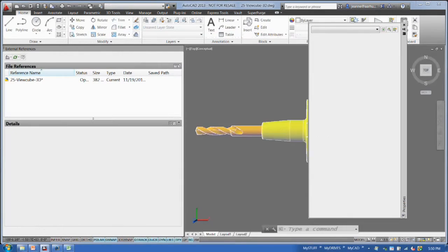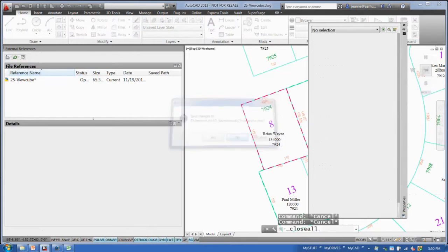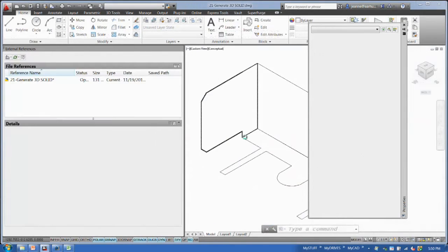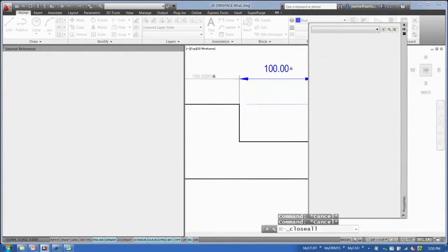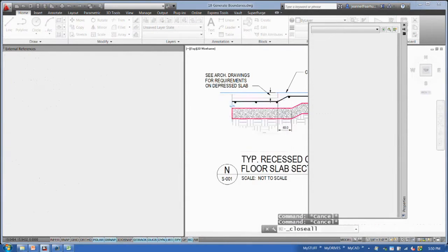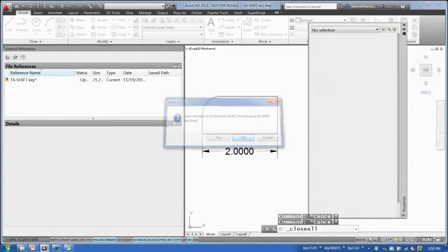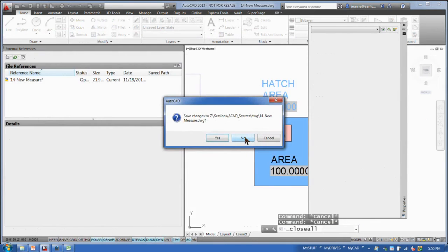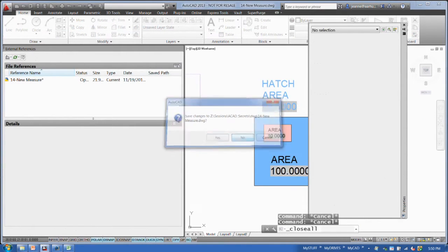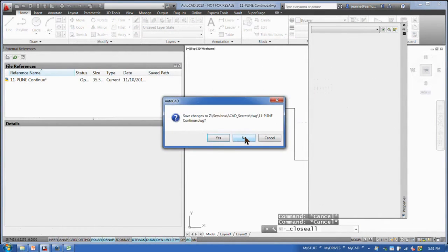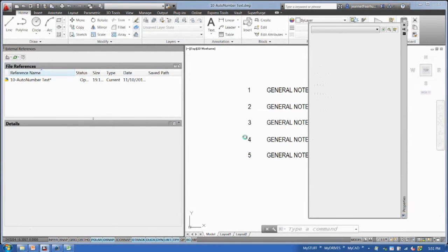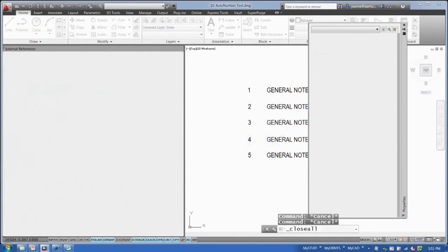Why would you pick the color white or black as opposed to using background color? Like, assuming you're doing it instead of placing wipeouts or text frame? Mm-hmm. Because sometimes I'm trying to match something else, a solid hatch that's in my drawing. Otherwise, yes, if you're just trying to emulate wipeout, you would use the background color. You're right. Yep.